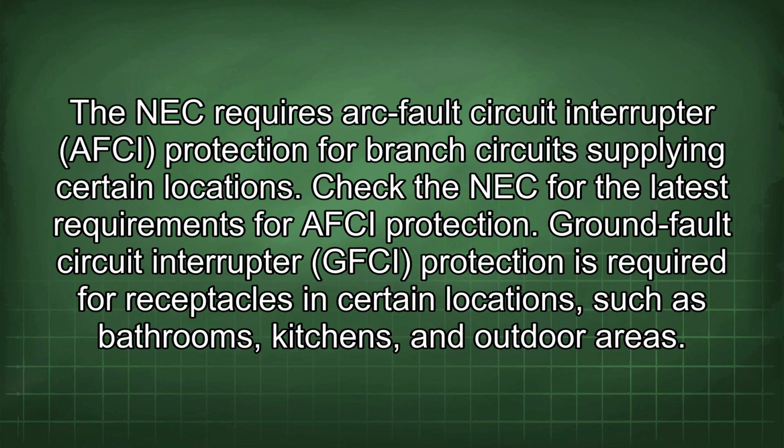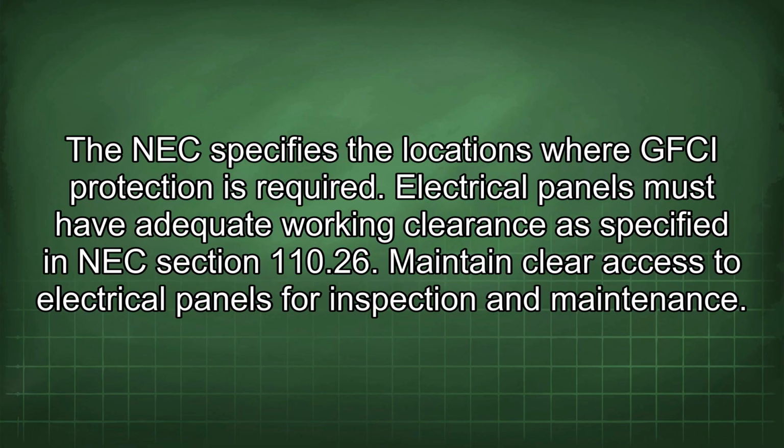The NEC requires arc fault circuit interrupter (AFCI) protection for branch circuits supplying certain locations. Check the NEC for the latest requirements for AFCI protection. Ground fault circuit interrupter (GFCI) protection is required for receptacles in certain locations, such as bathrooms, kitchens, and outdoor areas. The NEC specifies the locations where GFCI protection is required.